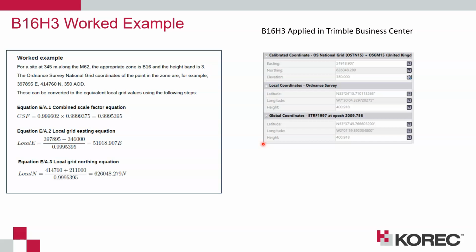The test results show no difference in the resulting easting coordinate and 1mm difference in the northing value, which isn't entirely unexpected when scaling is involved in coordinate systems. However, as the local grid zone settings are primarily used with GNSS survey methods on site, then a potential millimetre difference shouldn't be of too much concern.